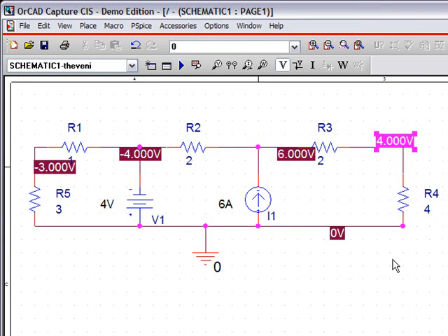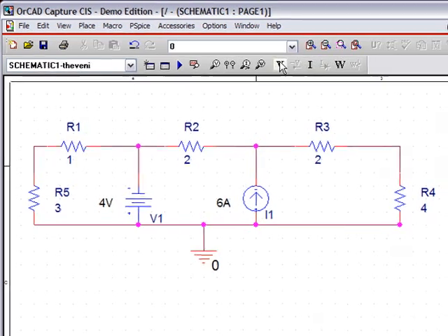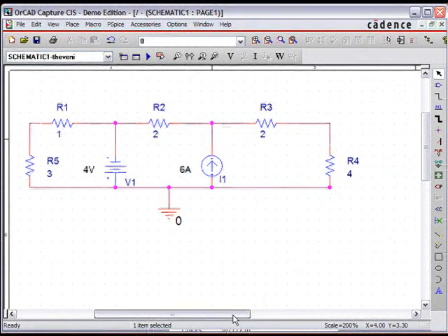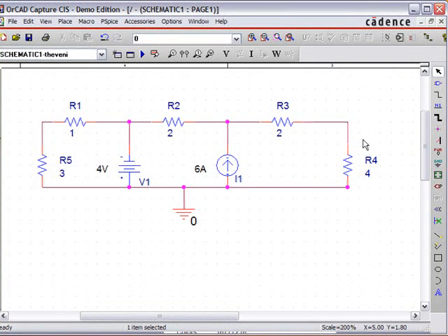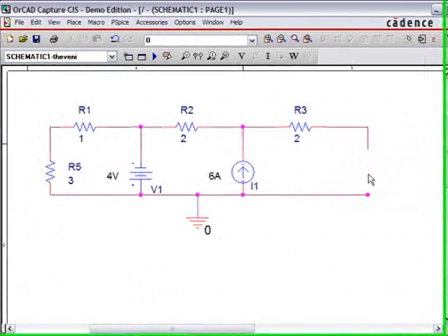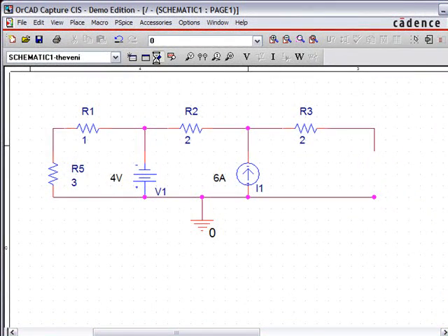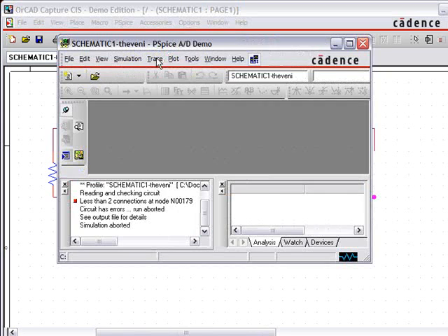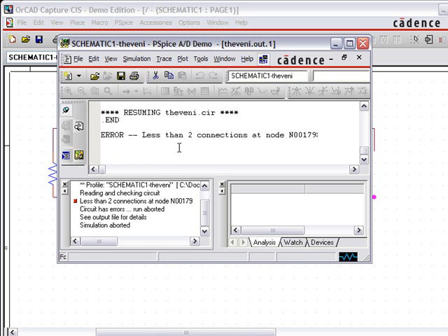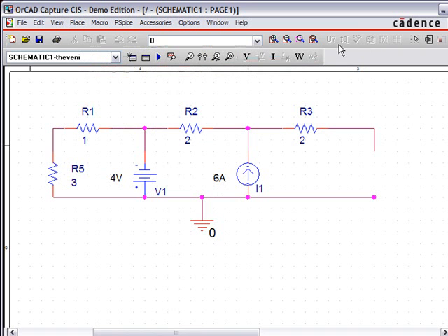But now let's use our Thevenin's circuit to find this voltage again. So what we do in Thevenin's theorem, we just take out this resistor R4 and measure voltage there. So let's just go ahead and do it. Measuring voltage right there won't work simply because we just got error here, so we don't have connection here. Well, let's just go ahead and simulate our open circuit with a large enough resistance.